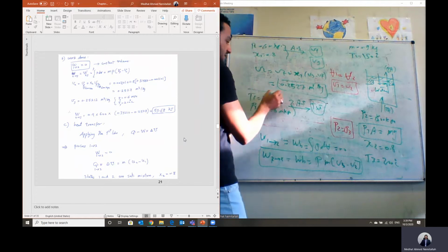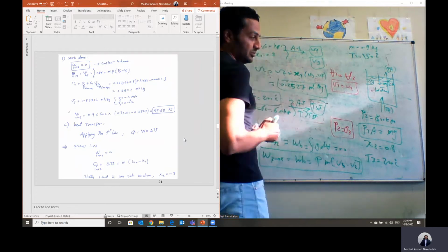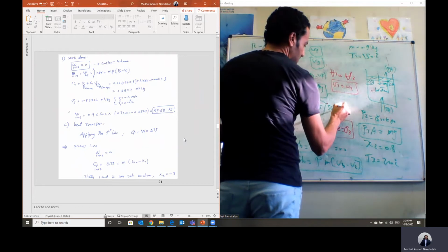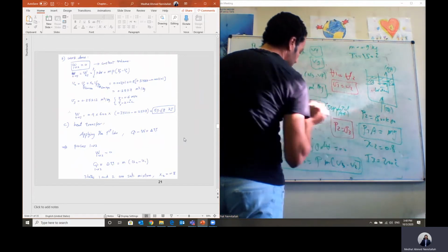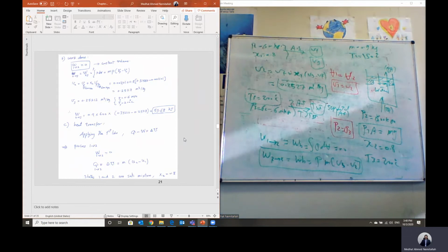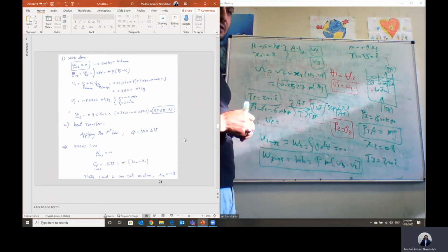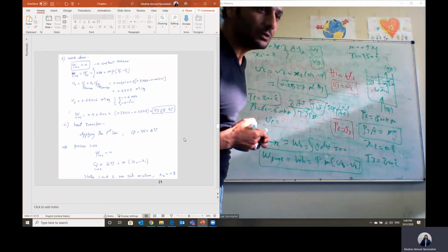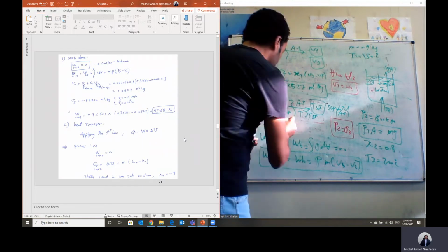You will find that the given temperature is greater than the saturation temperature. So the state is superheated, and I have to use table A6. Using table A6 with pressure equal to 0.6 megapascal and temperature T3, we can get the specific volume V3. Specific volume V3 will equal 0.352